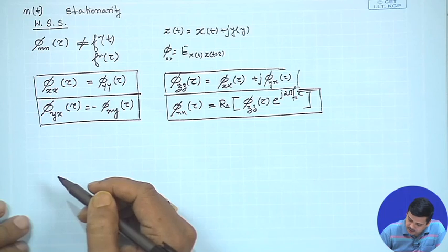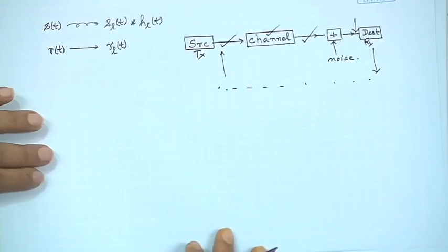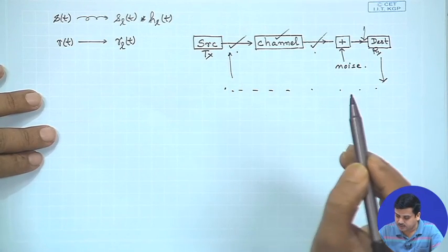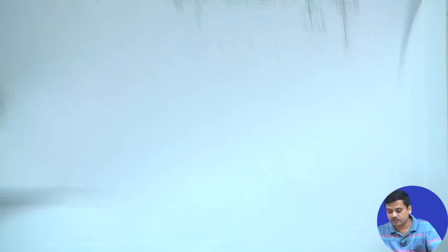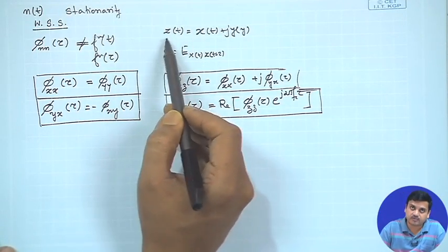Now what we will be interested in is this: we said that this is deterministic, but since these things are typically outcomes of a stochastic process, there is not much sense in actually taking the Fourier transform of these z(t)'s or n(t)'s. Rather, what we would be interested in are correlation properties and the power spectral densities, which are duals of each other in terms of Fourier transform.